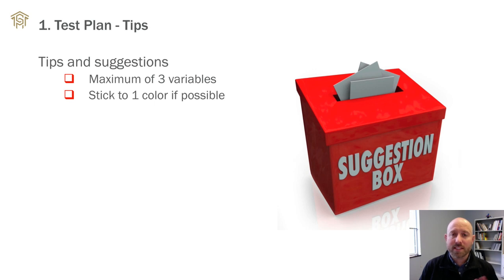Just print one color on it and see how that adheres, and then extrapolate the information you get from that trial to the other colors. Pretty much if one ink adheres, then they all will. But that's just an example. If it's possible to do it with one color, don't make it difficult on yourself. Identify what's important and stick with that.